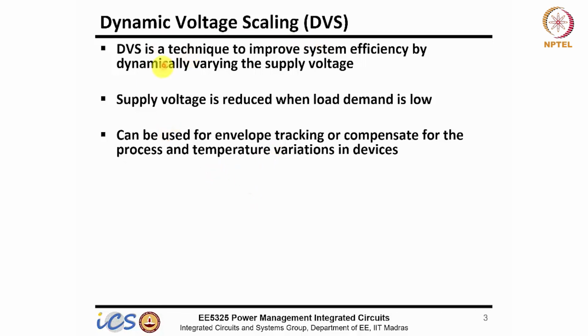Okay, so dynamic voltage scaling is a technique to improve system efficiency by dynamically varying the supply voltage. The supply voltage is reduced when load demand is low, and it can be used for envelope tracking or to compensate for the process and temperature variations in the devices.